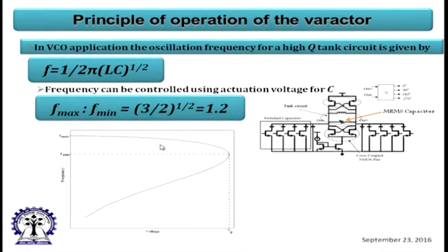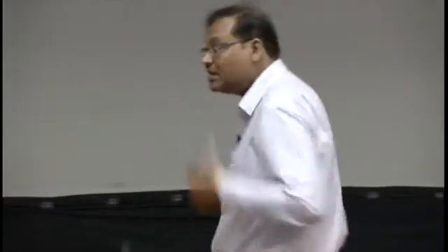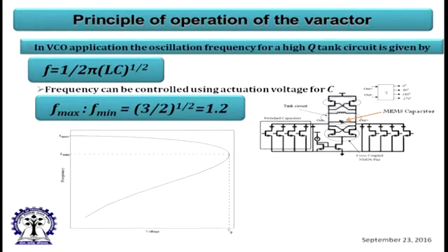Somebody has asked me, what is the logical thinking process? Am I going to the wideband? If you can have a tuner with the capability of a 20% change in frequency, then potentially it can give me a wideband kind of frequency tuning. Whereas in a normal LC VCO, the frequency tuning is limited to 4-5%, because you have this problem of KVCO. As I mentioned, your phase noise performance would be worse if you increase your KVCO. So, in that way, tell me when time is less.